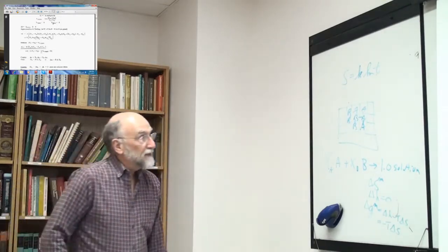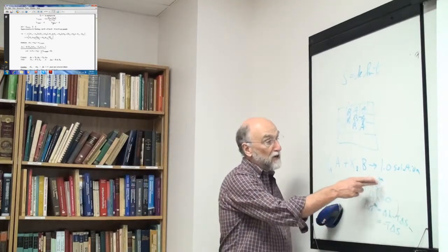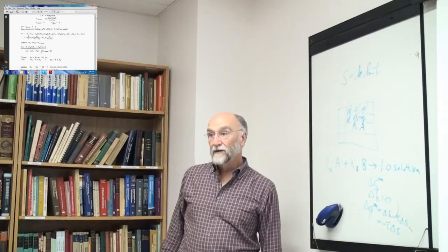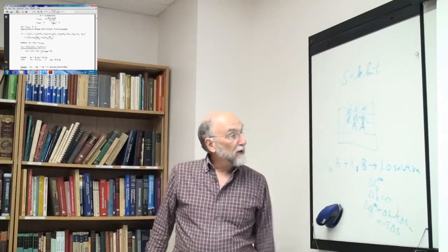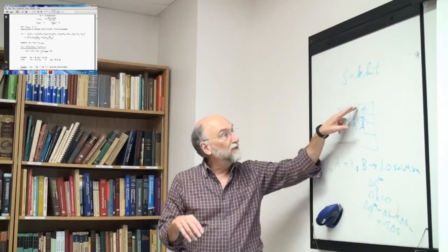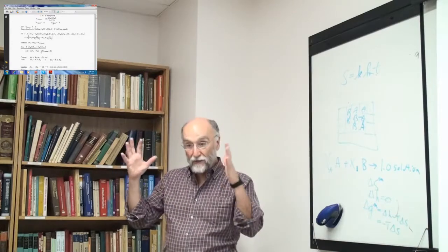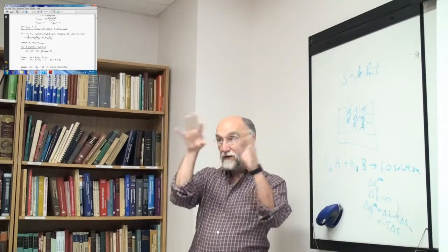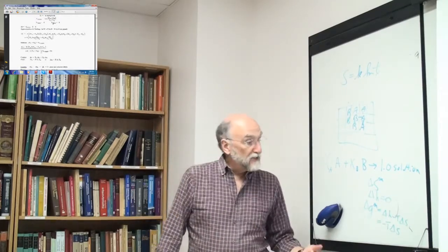What makes a solution ideal? Well, what makes a solution ideal, I already said, is what makes delta H approximately 0 and what makes the entropy approximately random, and that's if A and B are very similar chemically. Now here I've mixed them on a lattice. This same equation would apply for a liquid, in which case you don't consider this to be a crystal lattice, but you consider the lattice, in quotation marks, to be the instantaneous sites of the atoms. You imagine the lattice is frozen. You have positions of the atoms, the lattice is frozen, and you then distribute the A and B over the instantaneous positions. Actually, it's the same thing for a gas.